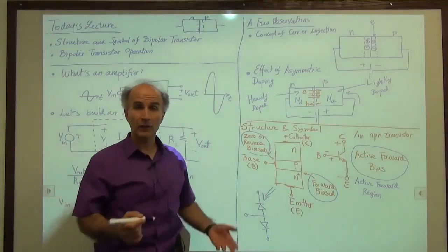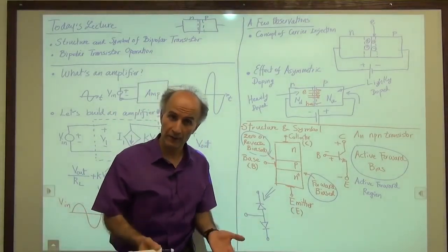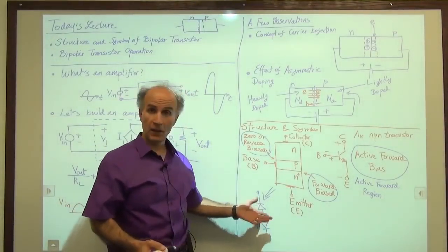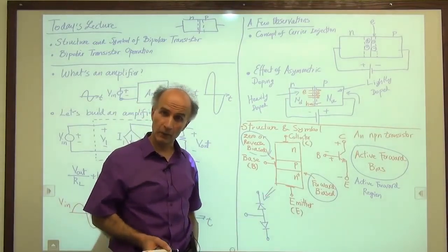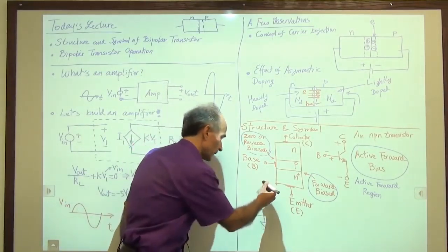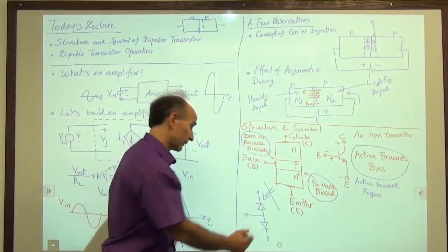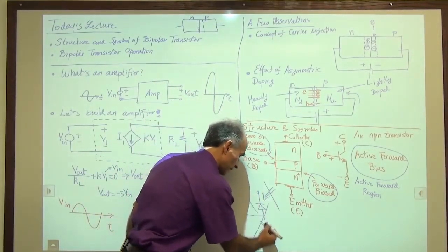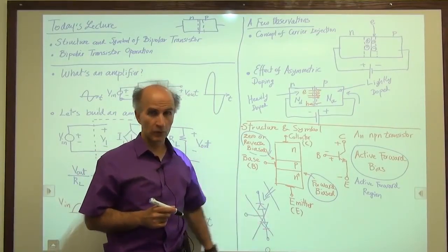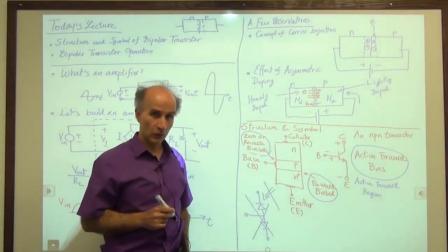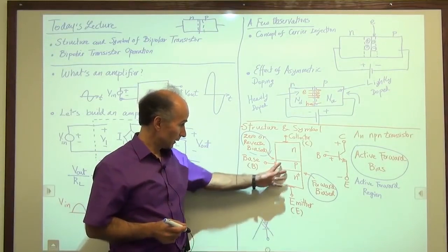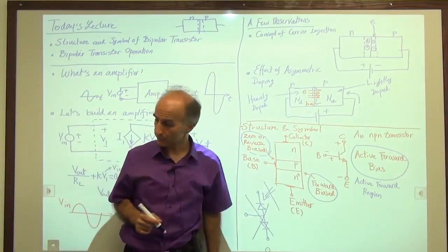Right? So actually, I don't need to buy a bipolar transistor from the market. I can go buy two diodes and hook them up like this, and that should operate as a bipolar transistor. But unfortunately, that is not true. So this is not true, and this is not a bipolar transistor. As we study bipolar transistors, we will see that this would not operate as that. So that's a word of caution, not to get confused between this and this, even though they look very similar.